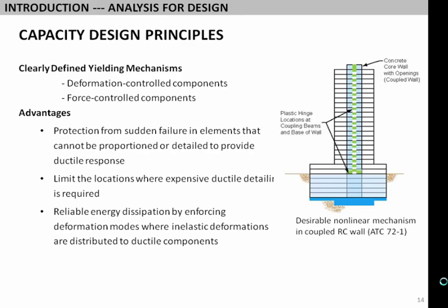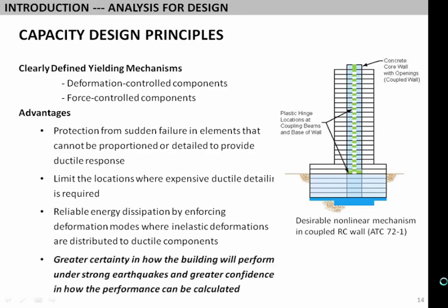And I think with new buildings, you have the opportunity to do that much better than, in contrast, existing buildings when you're rehabilitating. But from the standpoint of analysis, another big advantage of capacity design is that it really makes our analysis easier, okay? Because if we really have well-controlled ductile elements and we know where they are, we have a better chance of modeling them. And again, the messy elements that are force-controlled, that we're kind of shielding from nonlinear actions, we handle those elastically.